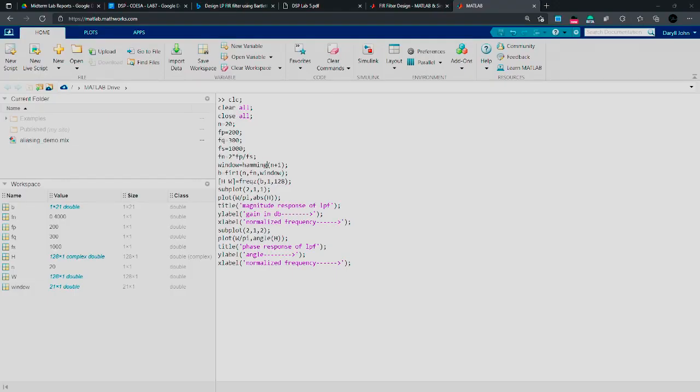This video aims to discuss and present the low-pass filter using Bartlett and Hamming window. So first, let's do the Hamming window. To do that, we'll just use the MATLAB function, which is hamming, with our value, which in this case is n plus 1, so that means 20 plus 1, so 21. With that, we'll use it to instantiate all the other values, and let's demonstrate how we'll design a Hamming window for a low-pass FIR filter.